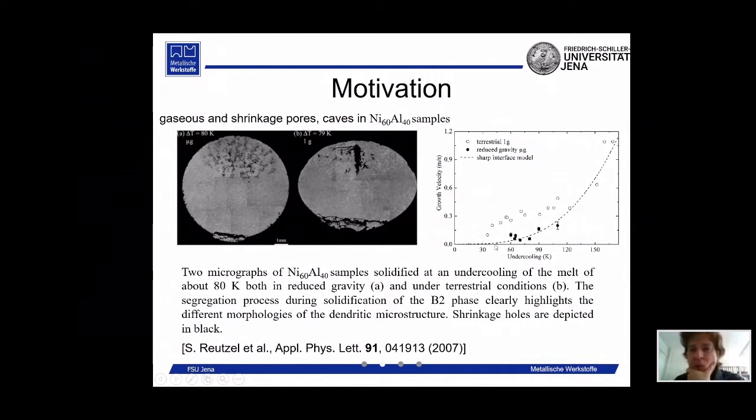So, a model without convection can predict well the data in the whole region of undercoolings, measured on microgravity and on the ground, beginning from some undercooling. What does it mean? It means that we can say that these points were influenced by convection, and convection influenced in such a way that we have increasing the velocity of crystal growth in this case. And we can say that beginning from some undercooling beyond the 120 in this case.